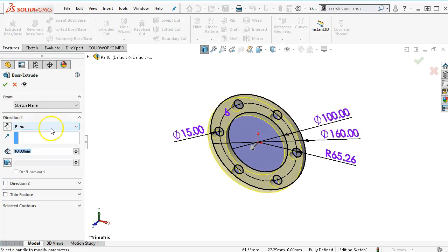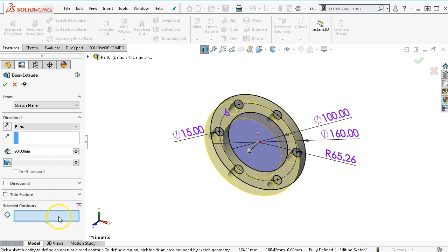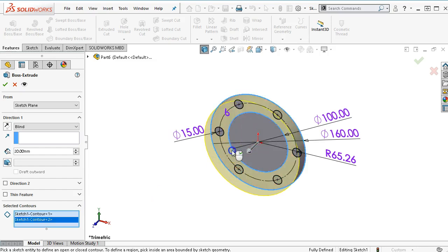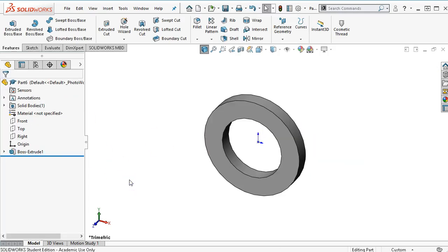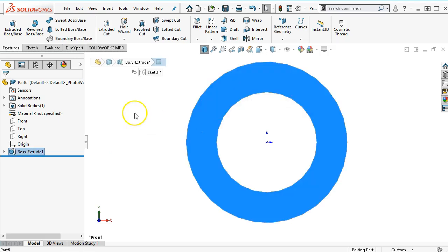So in that case, our thickness is 20 millimeters, and if I accept it, it will include all of the holes. Well, if I go back and say, no, I really didn't want to do that, and select the contours, that's going to make a full cylinder, and when I come to the interior contour, that is going to make it a donut, pretty much ignoring the holes that I included in the sketch. Alright, so I can manipulate this. 99% of the time I put those circles in there, I'm going to stay with them, and they're going to show up in this first feature.